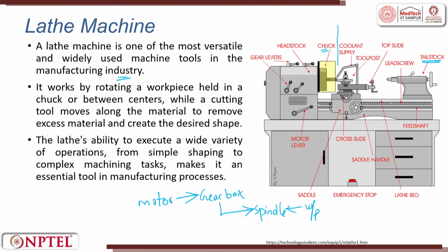So, in the tailstock, you will have a tip which gets advanced by rotating the handle. There will be a rack and pinion, or there can be a gear which tries to mesh. So, you advance the tailstock, it will go forward and it will lock.